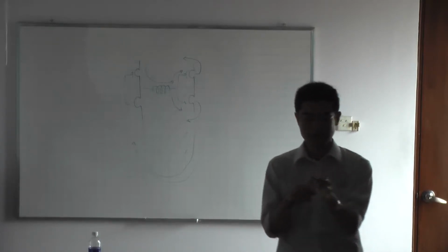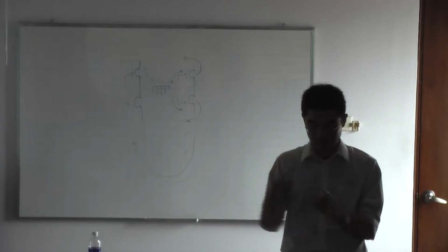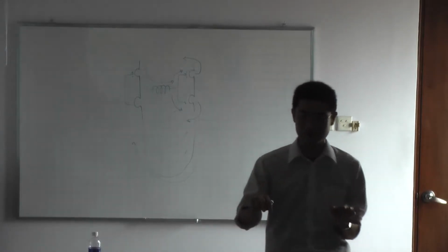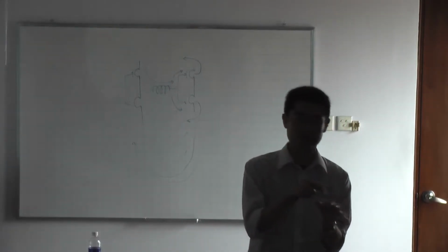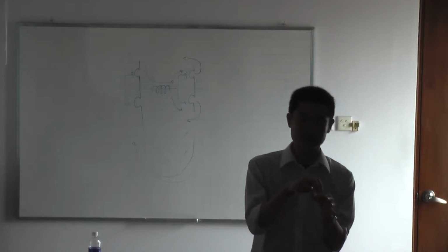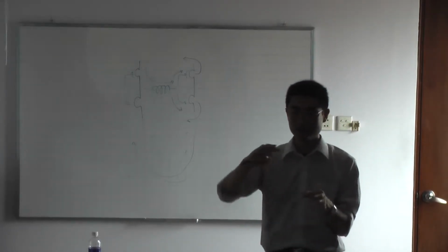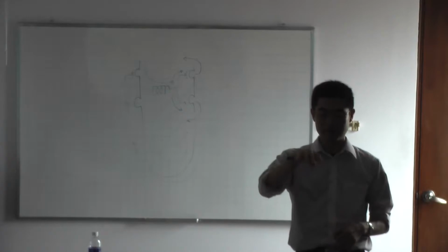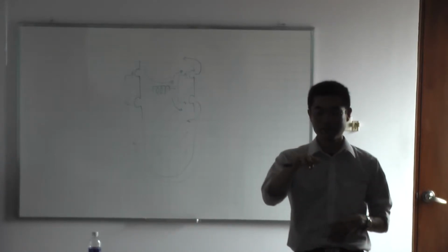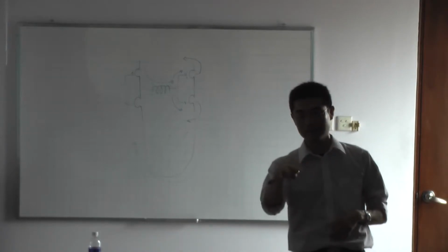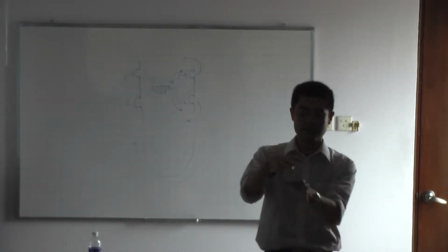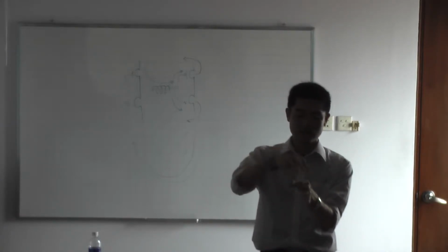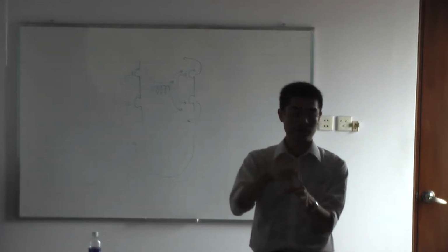And we use that plate. First, before touching a real device, we touch the gold surface and make a scratch to check if the prober is flat. When the prober is not adjusted properly, when we make a scratch, you will see only several scratches. But when it is completely flat, you will see scratches on all the pins.